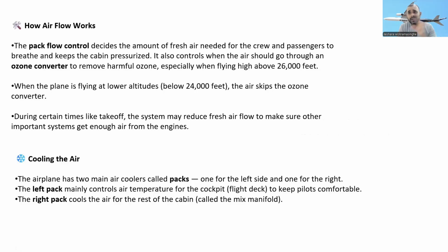Actually, they put in the ozone converter because of previous incidents. I remember it is taught in module 9, human factors. So that's why they put in the ozone converter. When the aircraft is flying below 24,000 feet, the air does not need to go through the ozone converter.